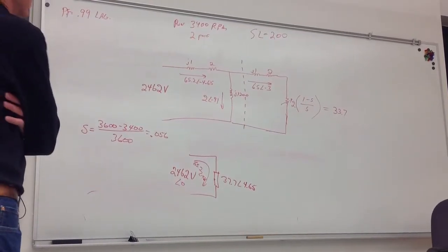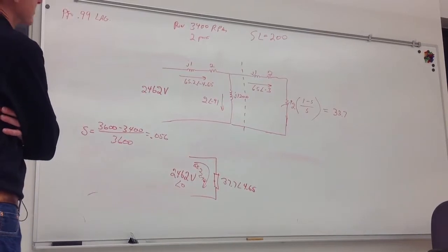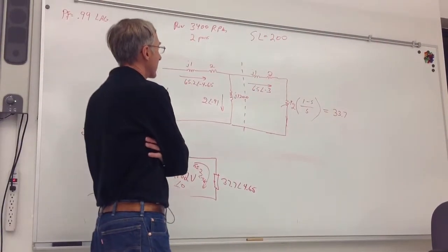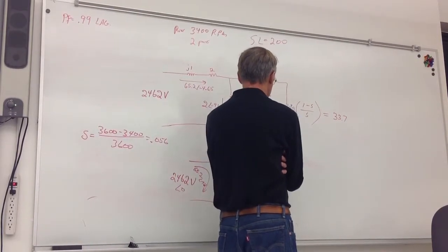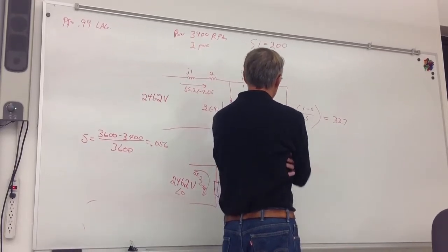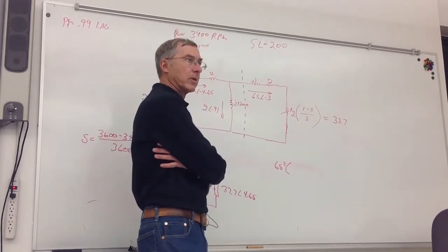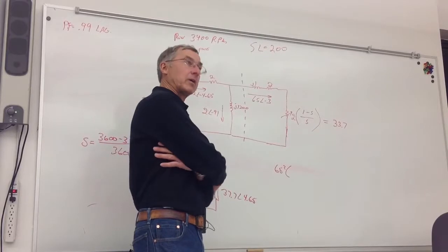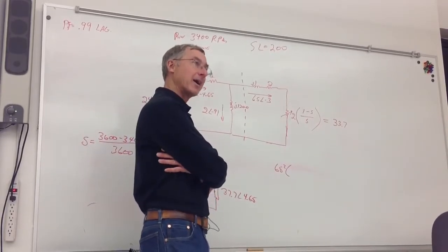That current, I squared R? Okay, give me the I's and the R's. 65 squared times j1 plus 2 plus 33.7. Well, 65 squared times j1, what will that give me? It won't give me real power. Well, what will it give me? We just got through working a problem using I squared X. What did we get? VARs.